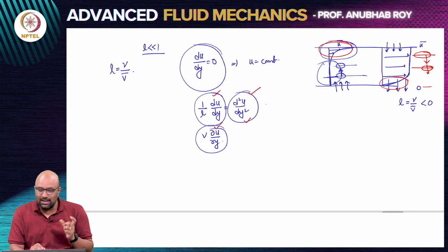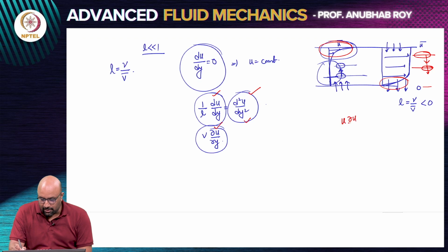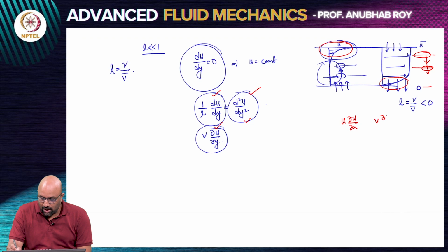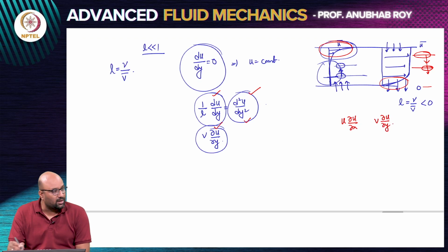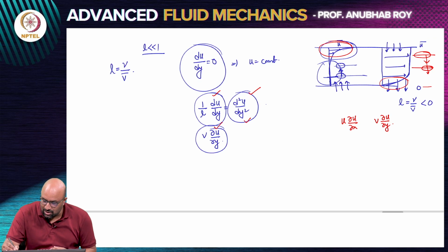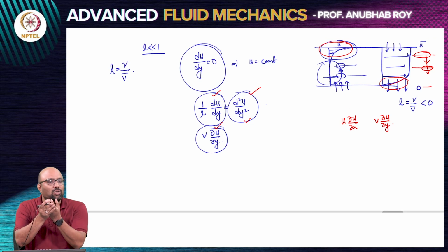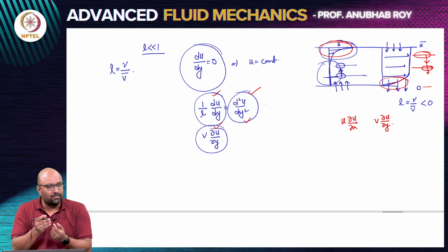So when we write the term u dot del u, that term signifies that you can have an acceleration or transport of momentum along the direction of motion, but you can also have a transport of momentum where faster moving fluid, if you have a flow with a variation in velocity, can be taken from one region and transported to another region, and thus change the momentum.